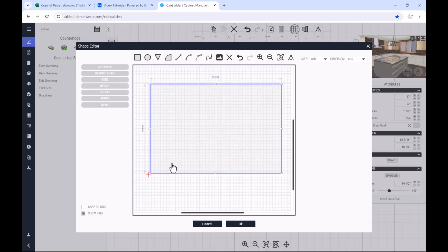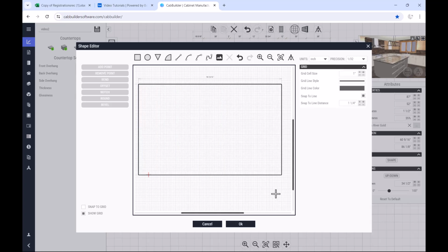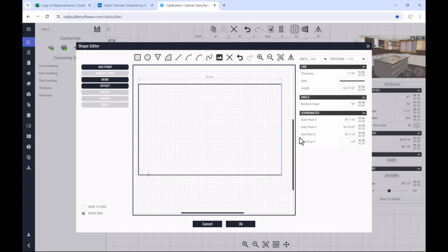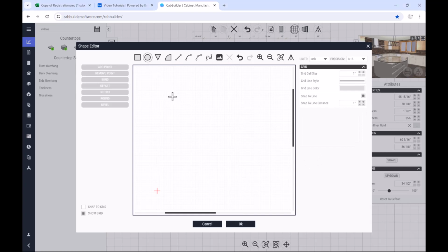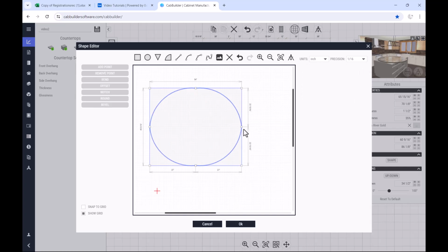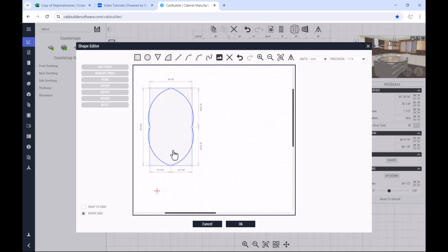At this point, if you would like to continue adjusting with the mouse, click and hold, then drag any of the points along the shape. When you are satisfied with the drawing, click in the grid space away from the shape to secure. Once the shape is secured, you may edit the shape further as demonstrated earlier. Be mindful when drawing a circle shape, as it is comprised of 4 arcs. These arcs do have limitations. That being said, if this shape is drawn too narrowly, the circular or ellipse shape may be disrupted.